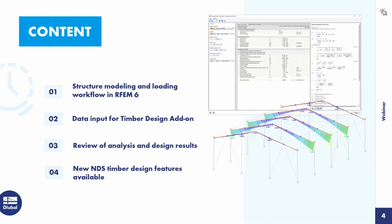Regarding the content over the next hour today, because we're still getting familiar with the interface options in the new generation RFEM 6, I will go through the structure modeling and loading workflow within this main program. Along the way, we'll take a look at the data input for the timber design add-on. So the huge benefit of RFEM 6 is that these add-ons are now integrated within the main program, so it will be part of this modeling workflow. Finally, we'll run our calculation to take a look at the analysis, but also the design results according to the NDS 2018. And along the way, I'll be sharing a few new features that we have specific to the NDS available now within RFEM 6.